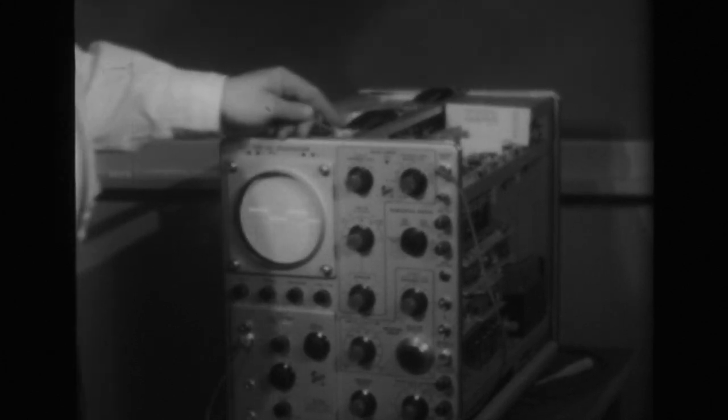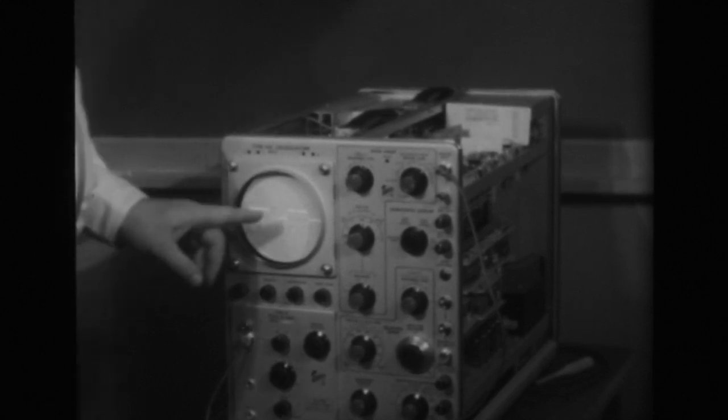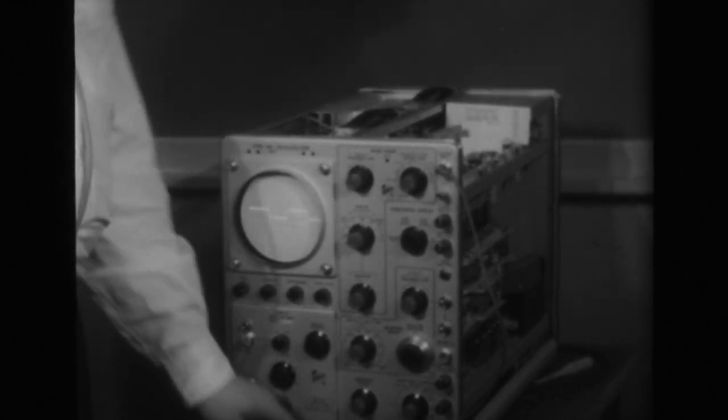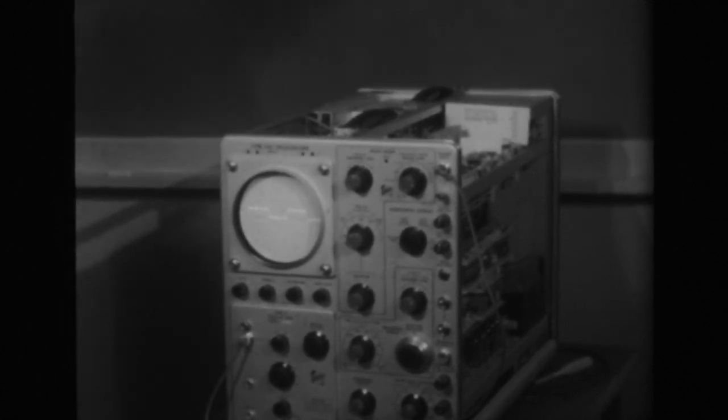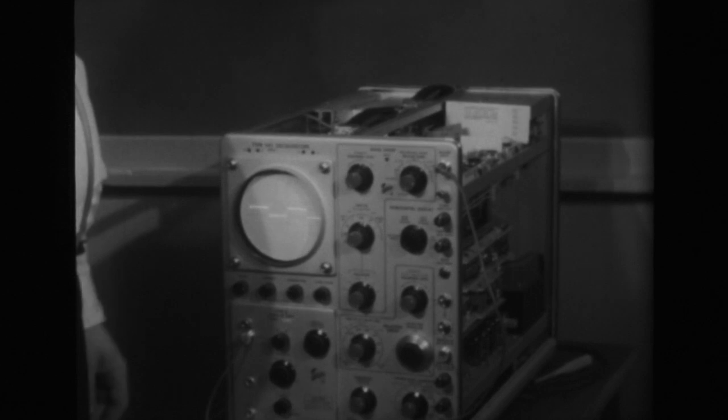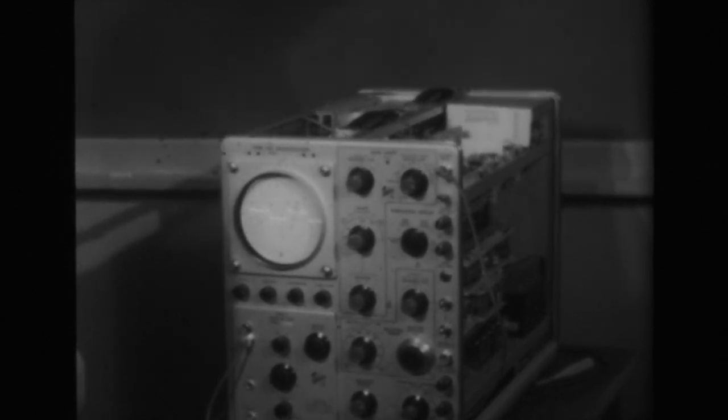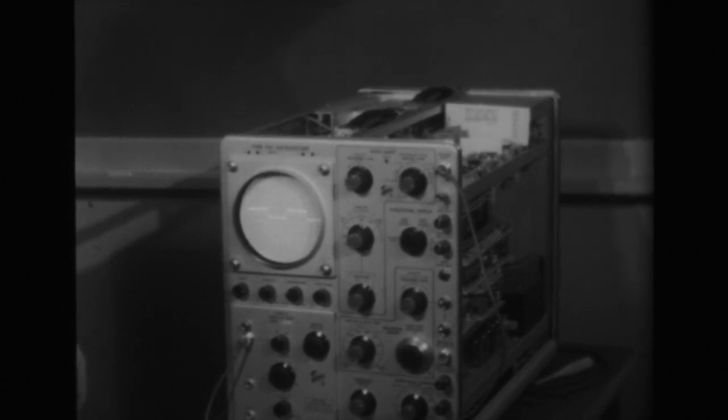Now, by checking to see that 100 millivolts will not cause a stable pattern on the cathode ray tube, we have indirectly set the hysteresis gap of the bistable multivibrator, the trigger shaper stage, to be about 1 2/10 to 1 4/10 volts.